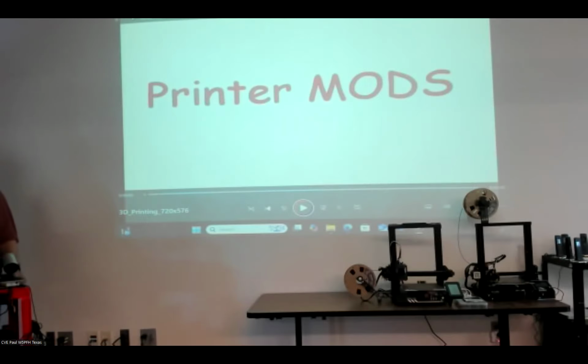I've personally tried the things on Amazon and other places that they call bed prep. I've seen a bed prep lubrication, bed prep oil, which to me just sounds funny when you're talking about 3D printing. But it's another type of glue on a sponge head that you lay down before you do your prints. Some of those chemicals are 30, 40 bucks a tube. For me personally, I found the best thing is that purple glue stick on a glass plate. Some use hairspray, which is another common one. Back to school supplies is the most cost effective.